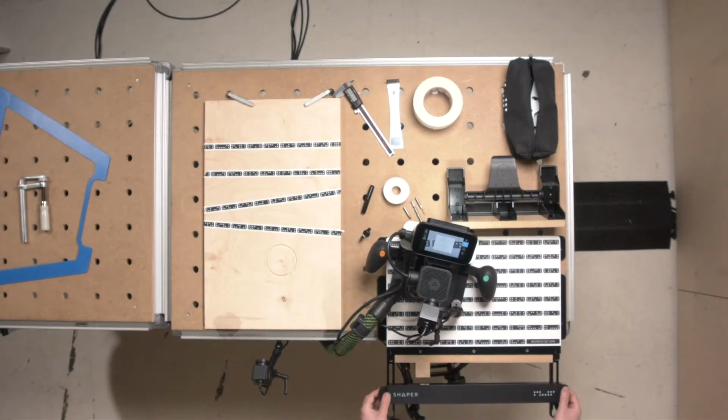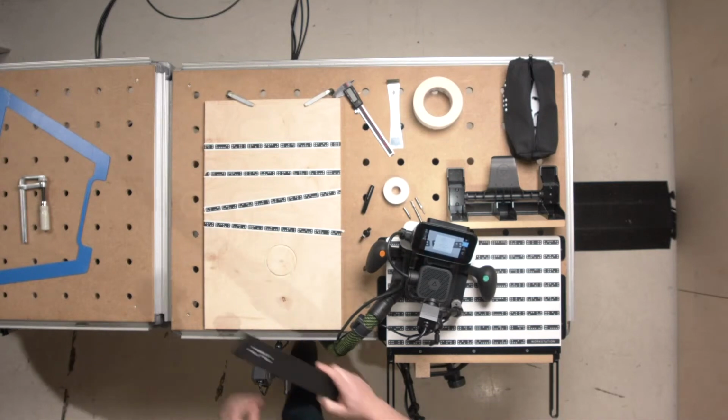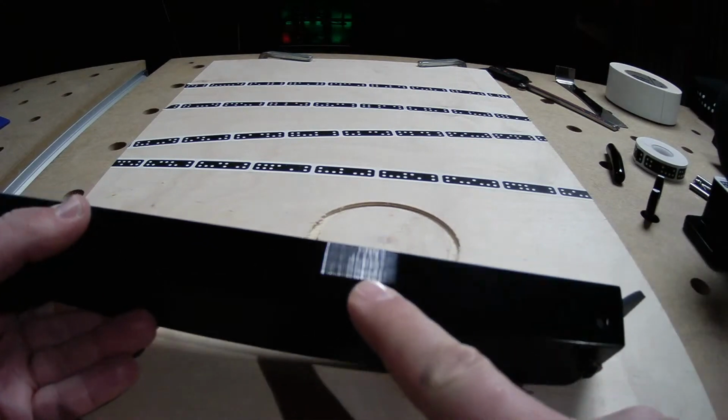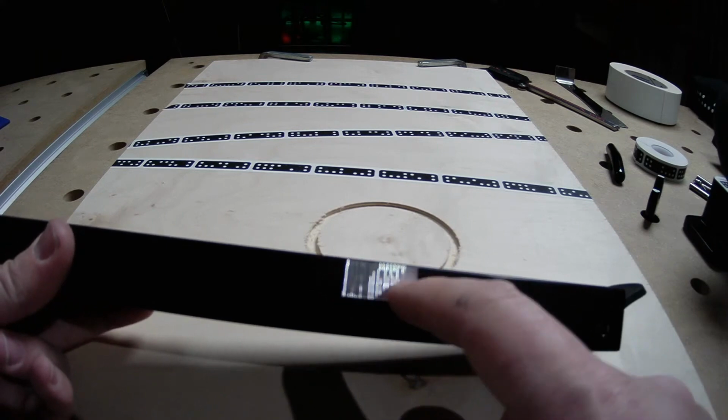Okay, so as you can see, the support bar slides on these arm tracks, and that allows you to adjust it any way you need to suit the project that's in there. But you want to be careful that you leave enough room in between what you're working on and the support bar. And actually, we have a perfect example of that here in the studio. If you look at the detail camera, this is what can happen if you get your bit too close to your workstation. You'll be milling aluminum, and you don't want to do that.